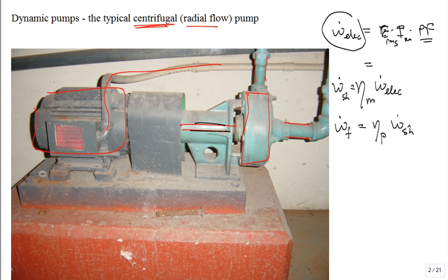All right? So where does the 1 minus the efficiency of the motor times the electric power coming into the motor go? If only eta of motor goes into the shaft, where does this go? This goes into heat. And a lot of times they have little fins on the motors, and if you go see a motor, you can sense it. It's warm and hot, and they even have places for a fan at the end of the motor, to bring air in and cool it off.